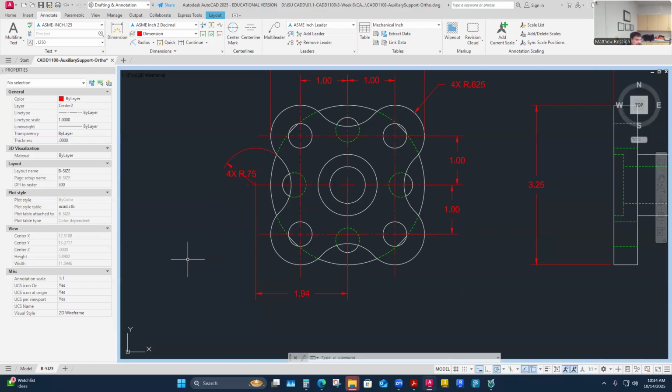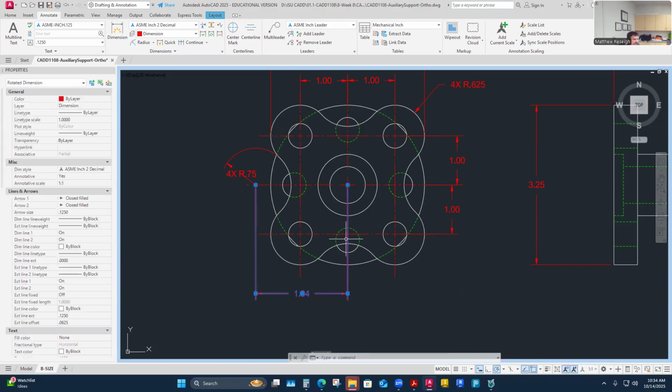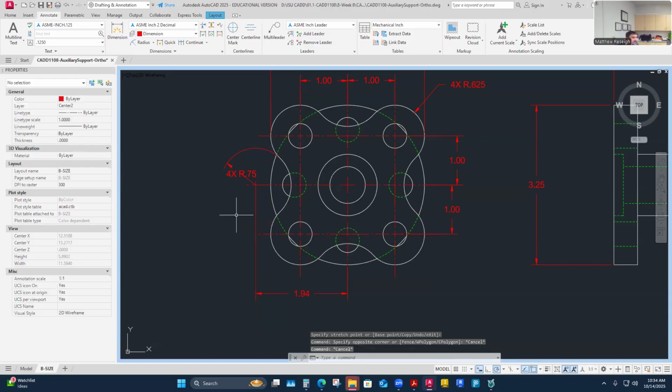And so you'd have to have a local note that says that's tangent to tangent and it's this diameter, right? The local note might be something that you would add a leader line for, point to that and say, if you've located this one, this next one is tangent to tangent. Yeah, that could be something. I would probably use dimensions though, rather than a note like that, as far as preference. It does say tangent to tangent, huh?